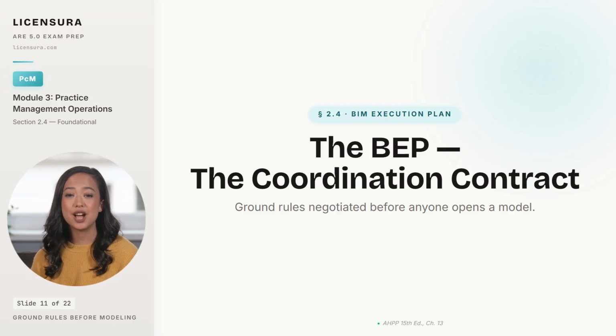Skipping the BEP is how you end up 8 weeks into construction discovering that the structural engineer was modeling at LOD 350, while the mechanical engineer was still at LOD 200, and nobody's models actually clash because half the elements are still placeholders. The BEP is the contract that prevents that conversation from ever happening. It's negotiated up front, in a meeting room, with every discipline in the same room, and once it's signed, it governs the project.